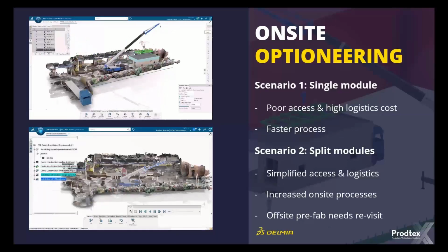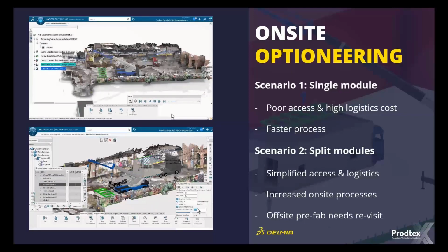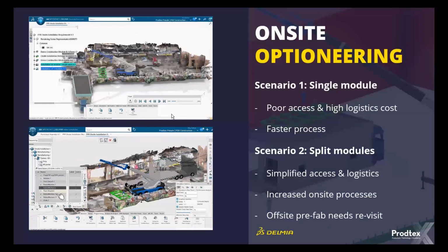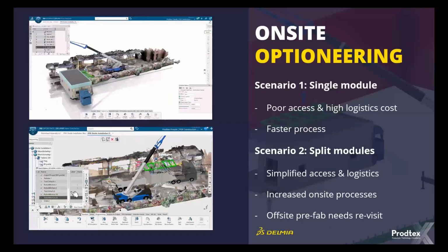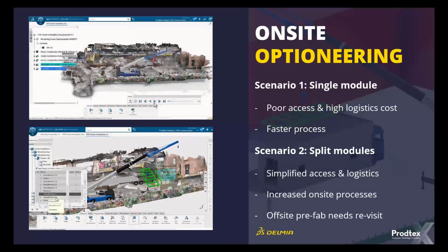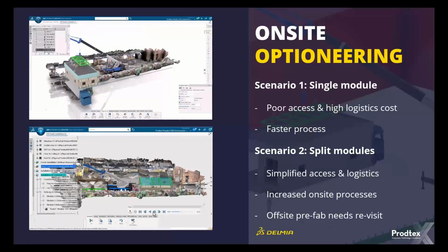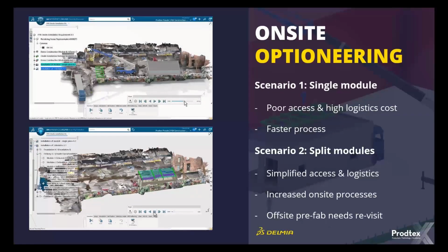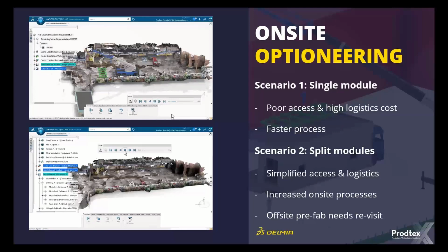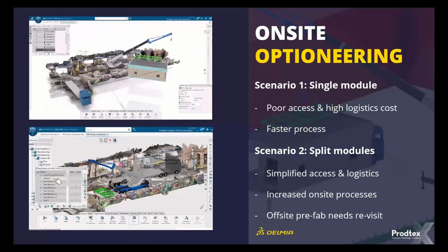We also saw that we had to give the design team some feedback. We could split the main body of the prefab unit into modules quite easily. However, we discovered the roof was not designed to be split up, and that's something the design team now need to take into consideration. Again, that's something you probably wouldn't have seen had we not used DELMIA and proved it out, but we quickly identified that as an issue. And because we're using a single source of truth, once the design team changes that and informs us of the change, it'll be replicated all the way through our E-BOM, into our M-BOM, and into our process, so we can quickly see the change as it happens. We're not having to sit and rebuild everything again just for a slight modification to the roof.